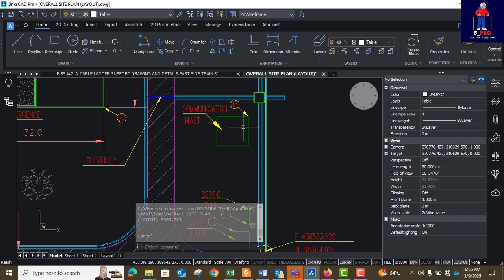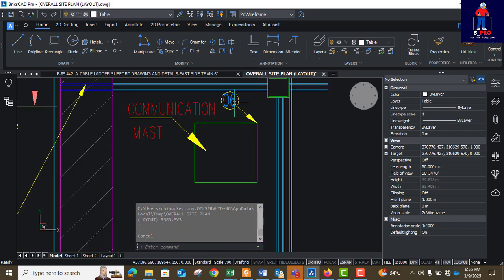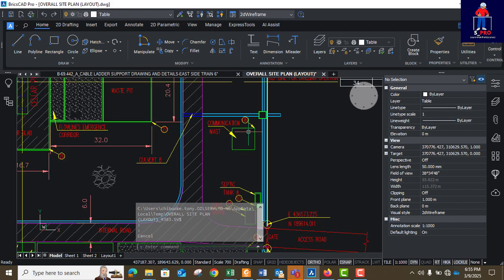You bring it in here and put it where it's supposed to be, and that might lead to a change in this coordinate, because the foundation might be smaller than the box we put here, and when it is smaller, you have to make some adjustments and put the correct coordinate. So that is what we normally do in foundation layout.